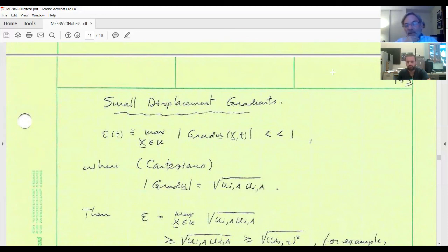Okay, and the reason is, let me spend another moment of your time here. Classical linear elasticity is for small displacement gradients. Not having the correct definition of the deformation gradient with the shifter leads you to a conclusion that linear elasticity is not frame invariant. A theory that's not frame invariant is trash. It's complete garbage. The reason being, let's say you design a building on the basis of linear elasticity, which people do every day.